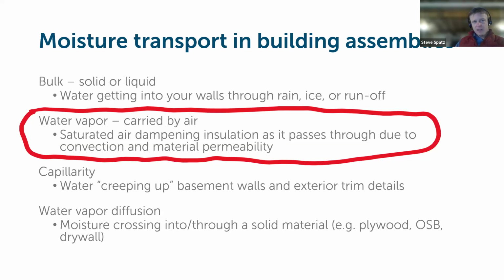And then secondly, managing on the inside face of the building what the actual assemblies of the walls and the roof and the ceiling are going to see to the occupant side, to the inside of the building, making those assemblies as airtight as possible as well, and using materials that are going to retard vapor flow through them as much as possible.